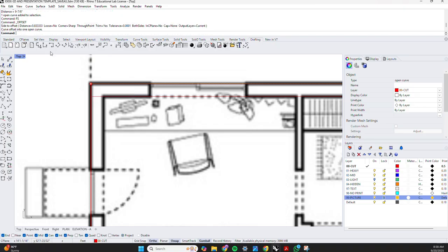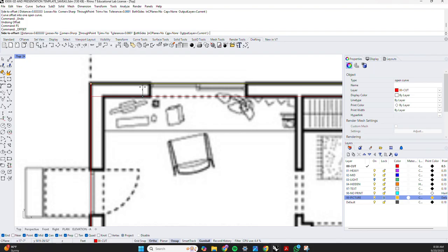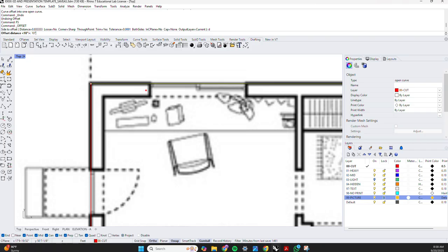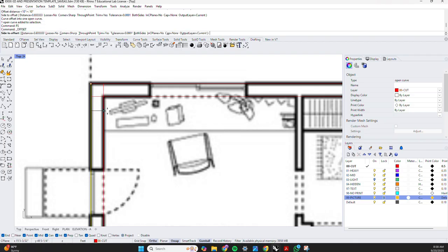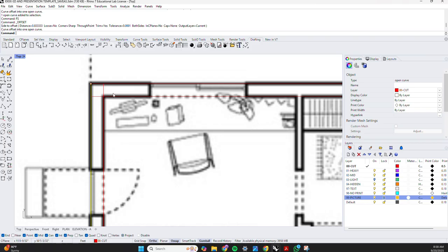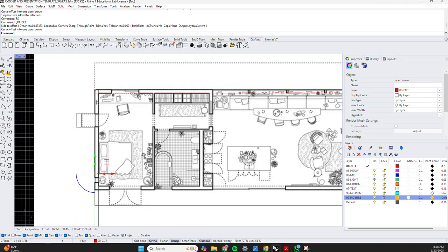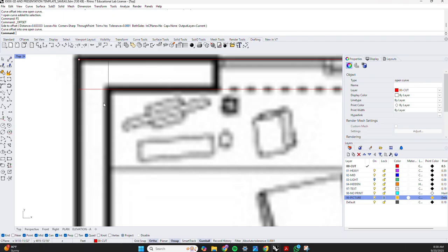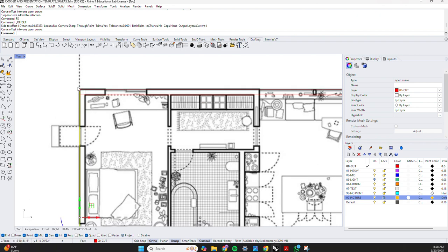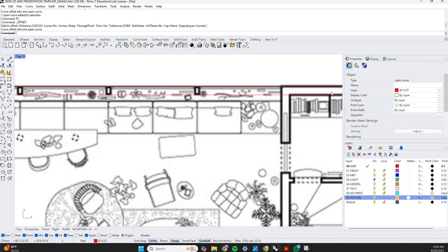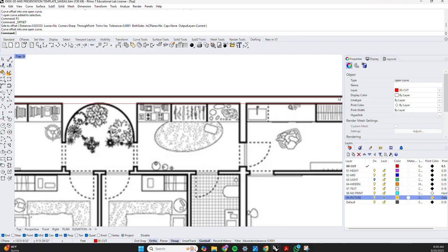So I'm going to offset this. My command is fs, by a distance, and that distance is 10 inches. Boom. I'm going to do the same here, even though when I did that initial trace, they were not quite the same. But in this project, they should be the same. The only reason they're not the same is because we can't zoom in enough or find the exact center. So you'll notice this comes all the way across cleanly. Great.